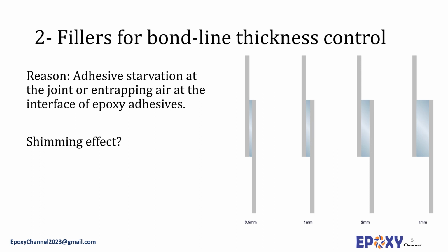Glass, nylon, polyester, paper, and cotton fabrics or mats are often used as a carrier in tapes or film epoxy adhesive systems. Glass or polymeric microballoons incorporated directly into the adhesive formulation can also be used for this shimming function.